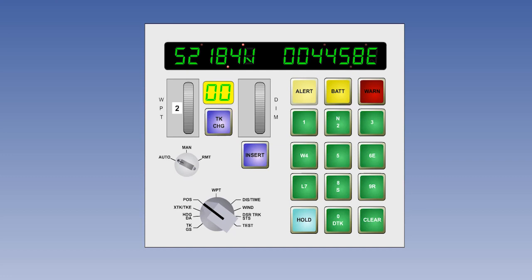The exact indications vary with the model of INS and the mode selected, but in most systems the alert light gives a steady illumination at about 2 minutes to go, changing to a flashing light at 30 seconds to go.